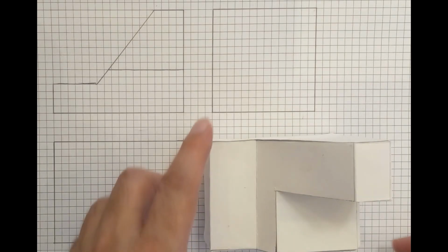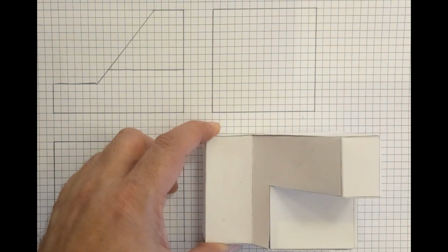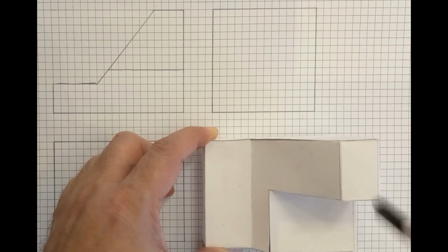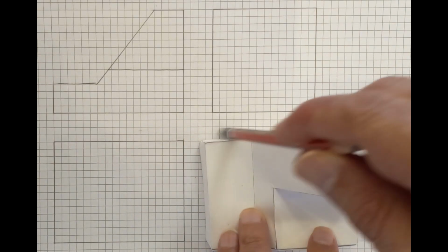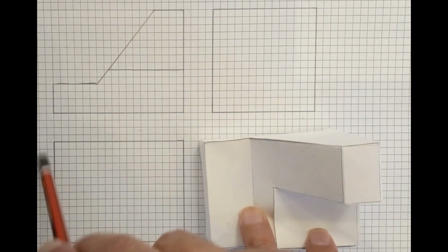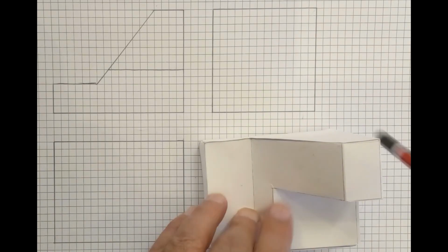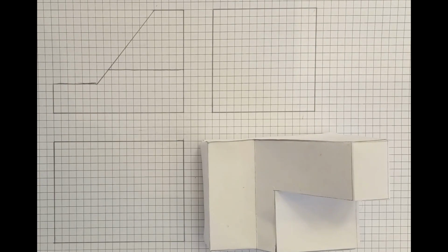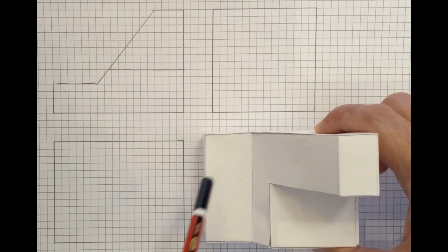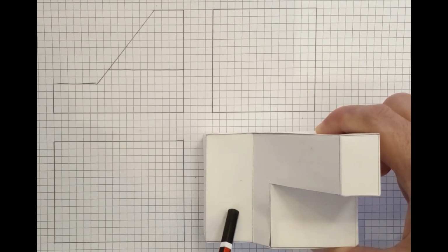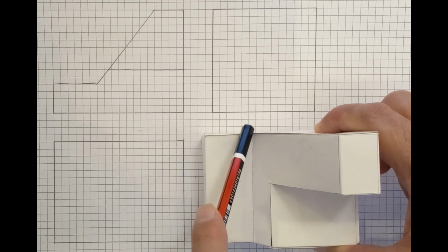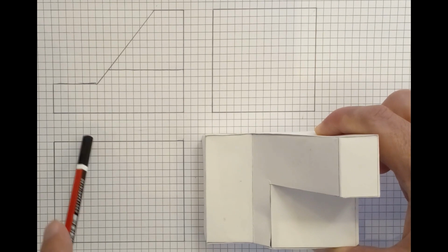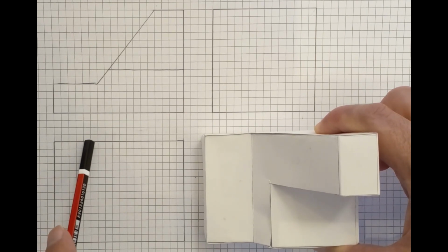The next view is the top view, which means we should look at the part vertically from this direction. This edge is this line, this edge is this line, this edge is this line, and this edge is one edge, represented by this line. If we start from the left, we will see this rectangle. This rectangle is bounded by 4 sides, as you know. These 3 sides already exist. They are here. So we need a 4th one here.